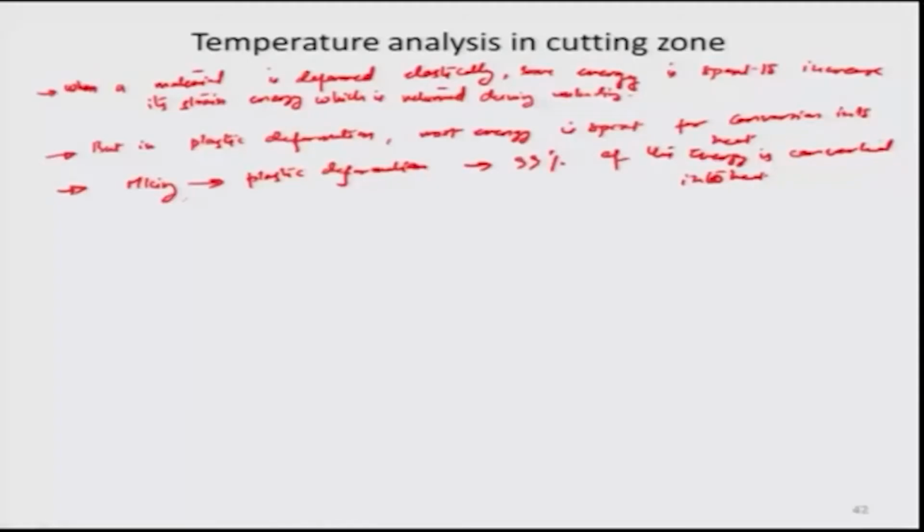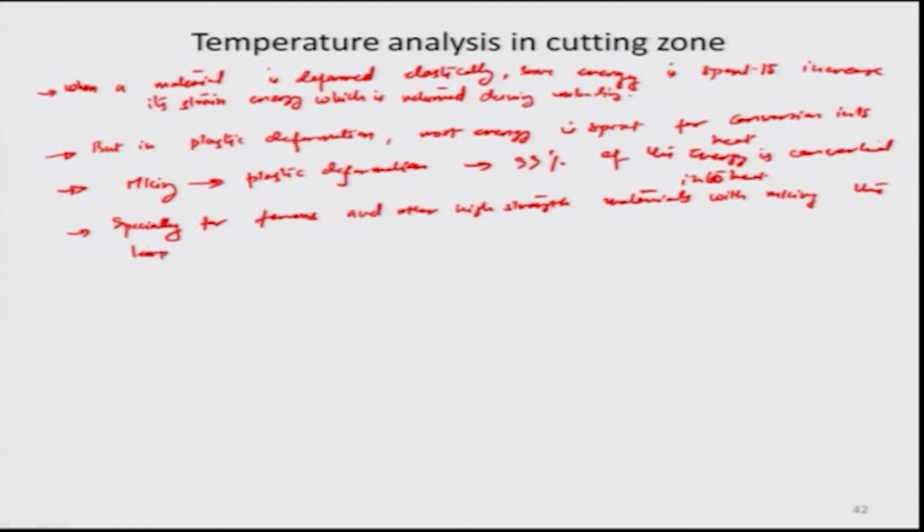So especially for ferrous metals and maybe some other high strength materials, with machining the temperature rises with speed of machining, and the tool strength also decreases.